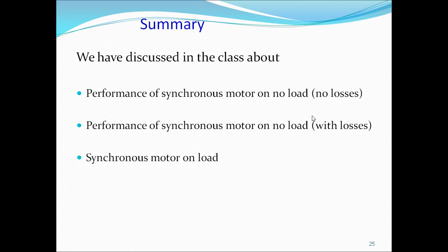Suppose we apply the load, then what happens? When we apply the load, the rotor progressively tends to fall back in phase by an angle called alpha. But it still continues at the same speed. Why? Because it runs at synchronous speed. The value of the load angle depends on the amount of load you apply on the synchronous motor. If you apply more load, there is a larger angle alpha. If you apply less load, alpha is less.